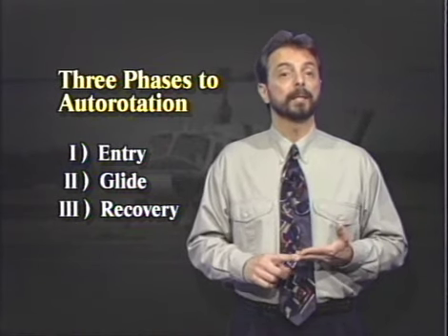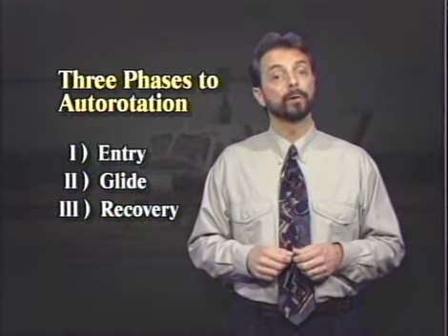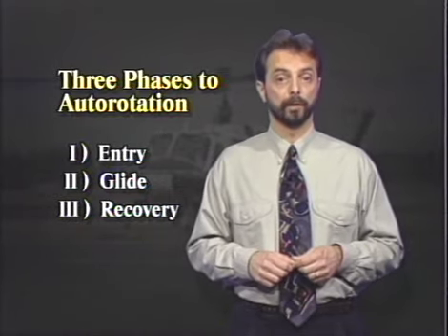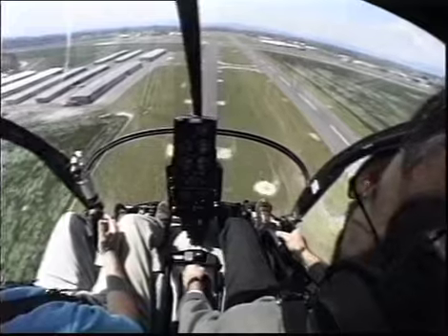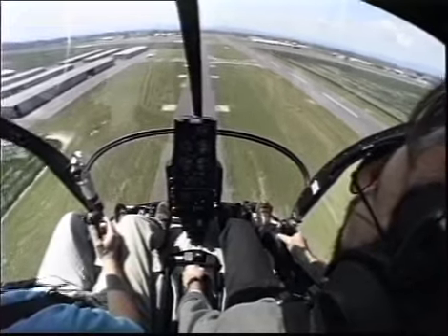The last phase is the recovery phase and begins when you're approximately 50 to 100 feet above the surface. Start by applying aft cyclic to initiate a flare.